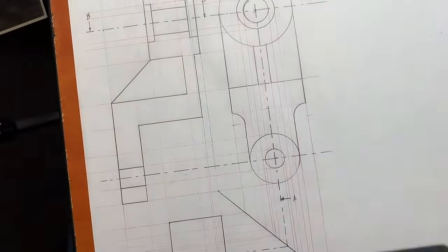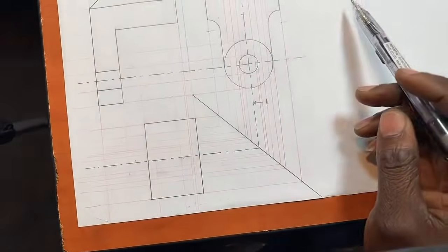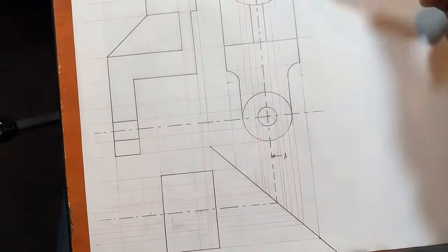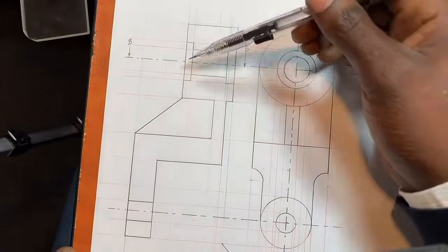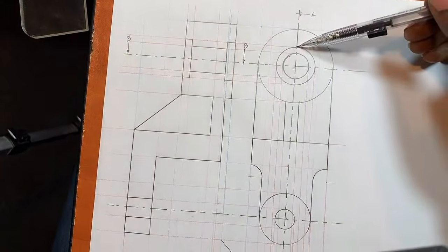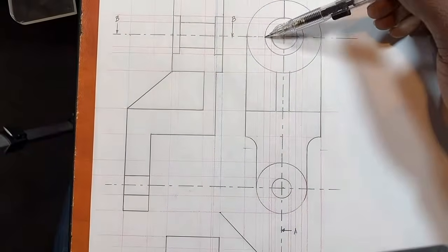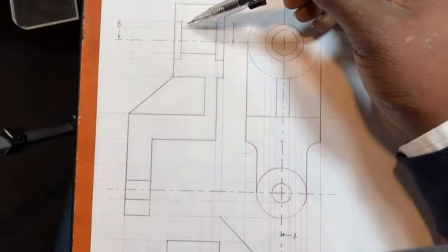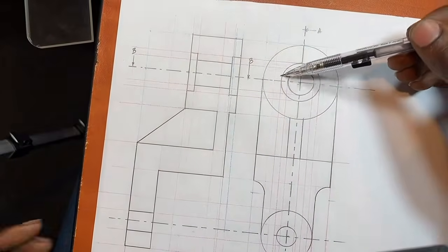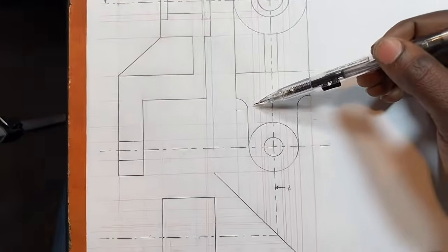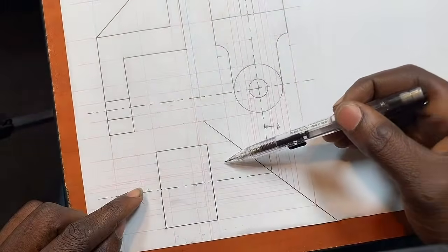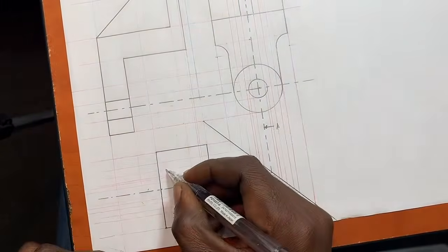How do you get it then here? We won't even record any dimension. You understand? So I'll get it like this. Come back to your front view. I'll trace it. That goes. Once it touches here, it's going to go this side. Remember, I started here. Trace it. That goes. Once it touches here, it comes this side. That goes. Once it touches 45 degrees, it's going to go, which means it's that one.